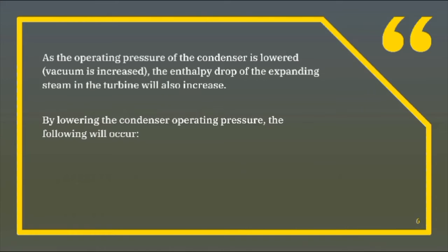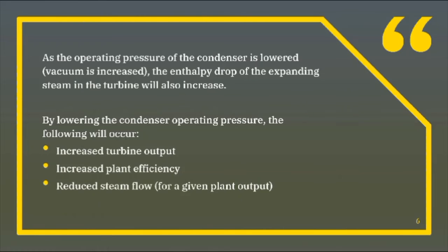By lowering the condenser operating pressure, the following will occur. Increased turbine output, increased plant efficiency, and reduced steam flow.